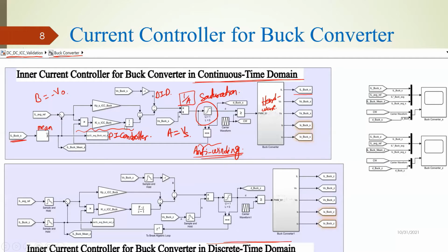So that is one. And then next time I turned on my control, the integrator already gave a very high value, and then boom. The speed of the motor went very high in a small time, and everything tripped.